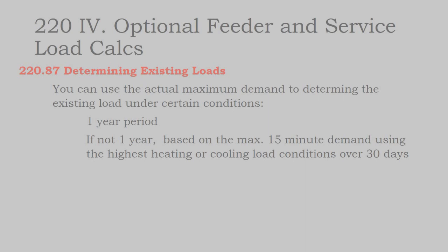So I had a client who wanted to do a 50 kilowatt array, that would be on a 40 kilowatt inverter, and he has a 48 kilowatt electric service, 200 amps times 240 volts. A volt times an amp is a watt, so that's 48 kilowatts. And so he wants to max out his service connection and do the largest possible array he can, and just sell back a lot of the electricity to the grid at wholesale pricing.